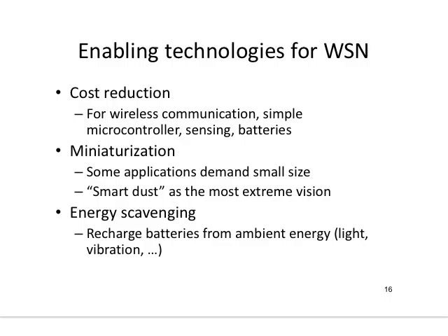An example of this is Raspberry Pis, if somebody has heard about it, or Intel Edison. So these are microcontroller boards, which are like small computers. They even have USB and Ethernet connectivity and so on and so forth. And you can easily interface a wireless radio to these nodes. Or you can interface different types of sensors to measure gas, temperature, and a bunch of things.